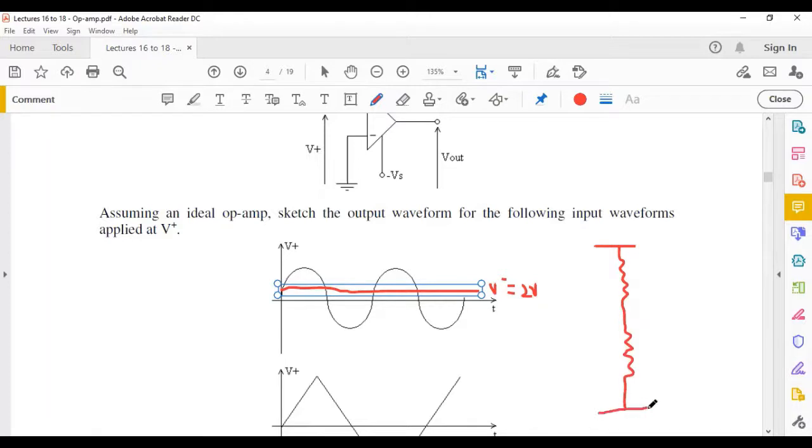So if you have something like this, and then you put this at 5 volts. If you want to get 2 volts here, you can put this one at let's say 2 kilo ohms and this one at 3 kilo ohms. So you can put 2K here, so that you don't have large currents. So if you do voltage divider now it is 2 over 5 times 5, so you get 2 volts, and then this point there is going to be at 2 volts.